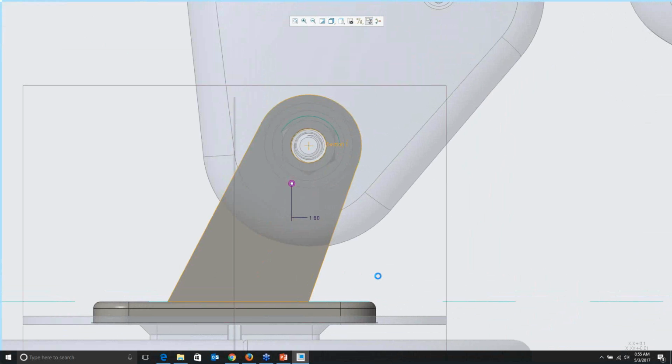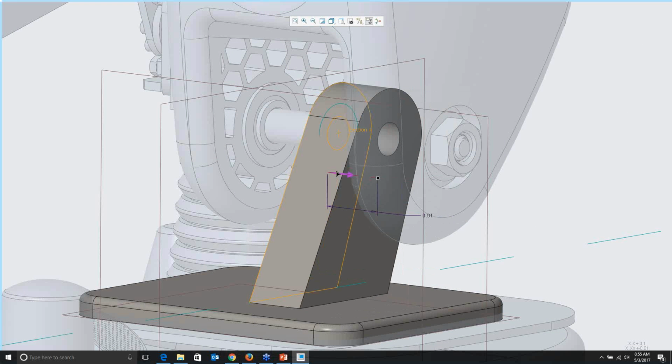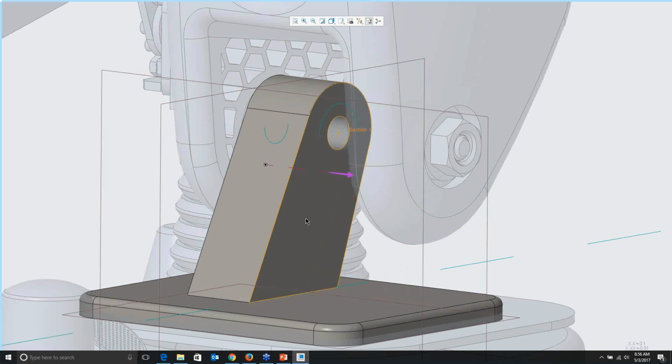Now, next up in here, let's start designing this extrude over here. I'll extrude and let the geometry itself control the extent of my extrude, right? So I'll say let's extrude up until that surface, that side surface over there. And we'll right click, and again, this is what I meant by easier access to side 2 features.